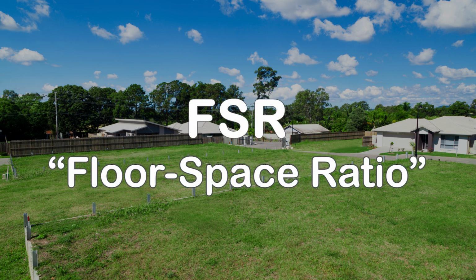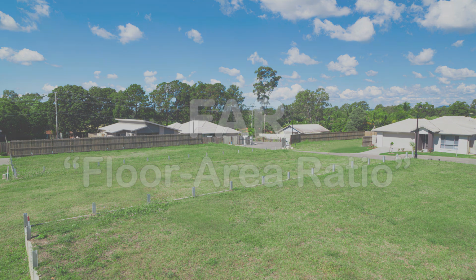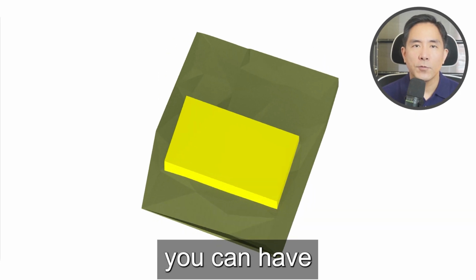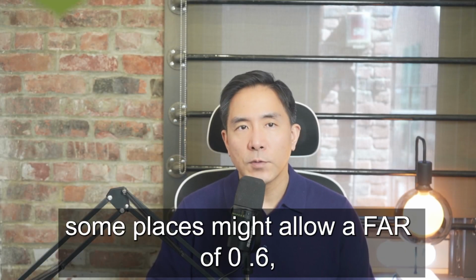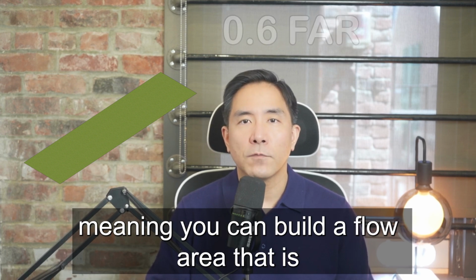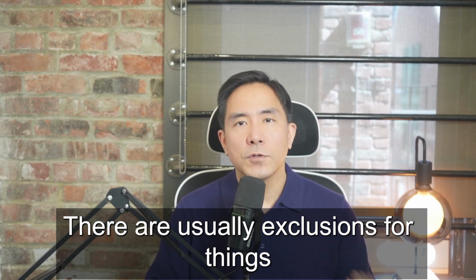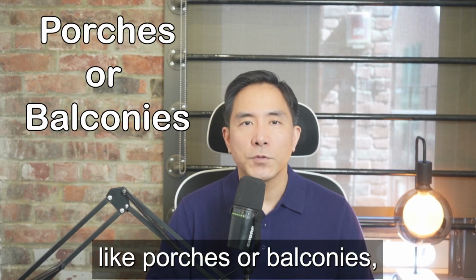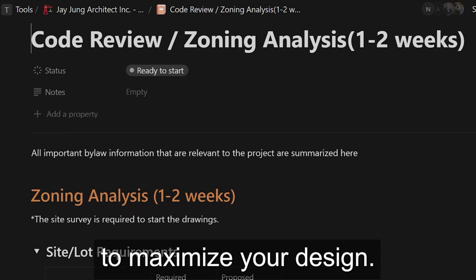Density, also called FSR, floor space ratio, or FAR, floor area ratio. This measures how much building area you can have relative to the size of your lot. For instance, some places might allow a FAR of 0.6, meaning you can build a floor area that is 60% of your lot size. There are usually exclusions for things like porches or balconies, so always check with your local bylaw to maximize your design.